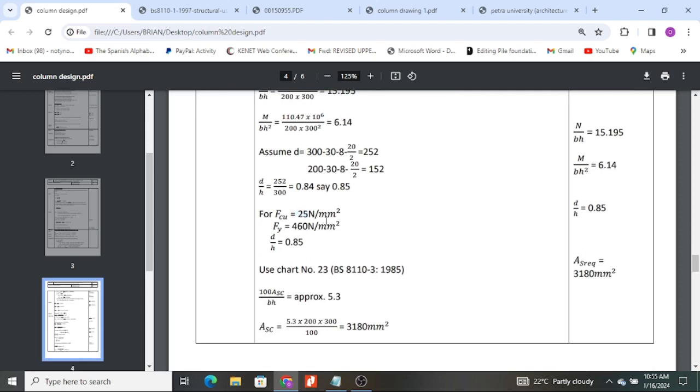The 20 I was using is so that we can be safe, but as I have been stating all along, you can still use 25, but ensure that this class is achieved on site, because the reason why most structures come down is because, number one, concrete. People have focused so much on steel that they forget to supervise or to ensure quality control when dealing with concrete.